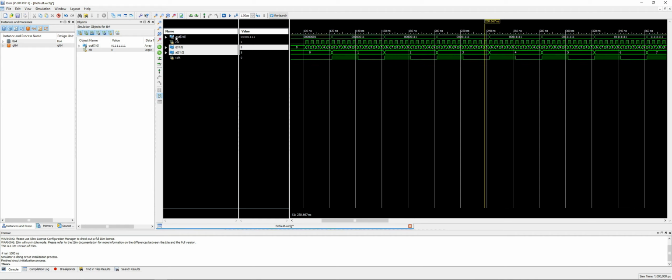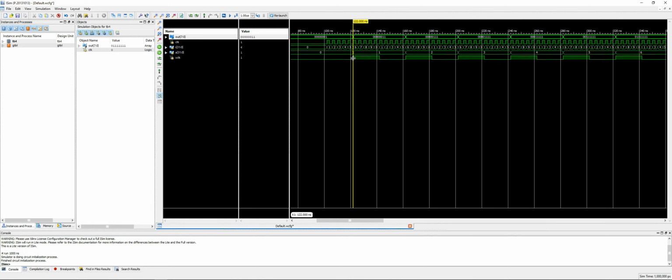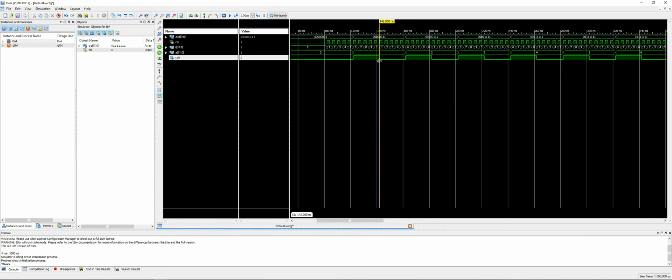See the output now, the out here represents our pattern for the LED, right? The pattern of the LED propagates from 1 until 1 1, and then after that 1 1 1, according to the slow clock. The slow clock here, the time period. At every positive edge of the slow clock, the LED is going to change the pattern. After that, you retain on the 0. Then on the next positive edge of the slow clock, you change to another pattern, and so on and so forth.